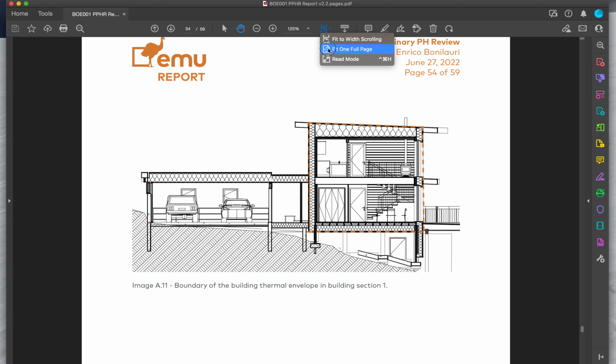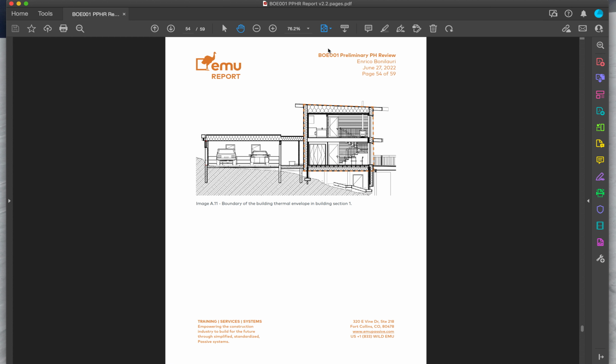So Appendix A is just a reminder of that, and that becomes very helpful in buildings that are more complex than this one to show did we include that crawl space inside the envelope or not? Is that crawl space for us conditioned? Do we recommend it to be conditioned or not? Is that attic conditioned or not, and why?